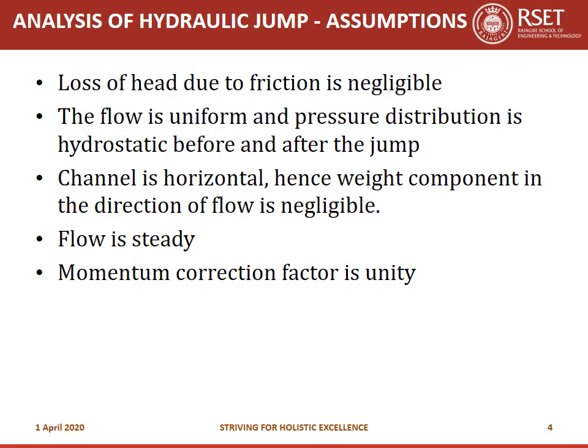So now we are going to derive a mathematical expression for hydraulic jump. We're going to analyze the hydraulic jump. Before analyzing the hydraulic jump, there are a few assumptions that we should keep in mind. One of them is that the loss of head or loss of energy due to friction is negligible. That is, in the free body diagram that we're going to draw, we will not be considering head loss due to friction.